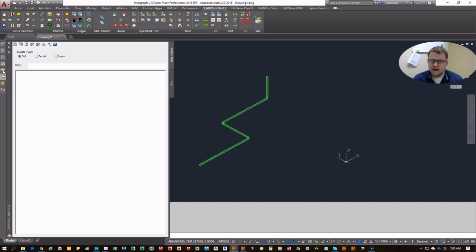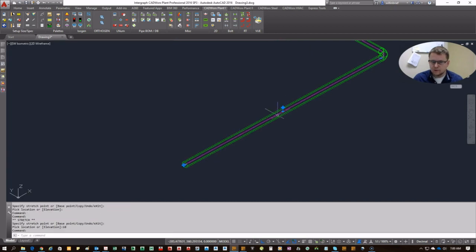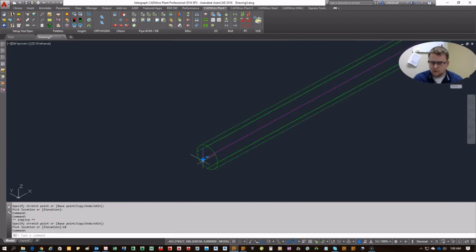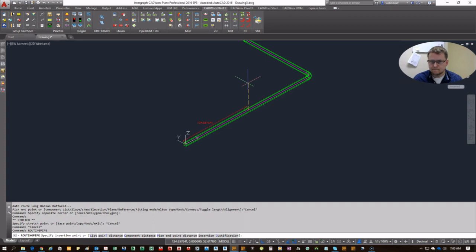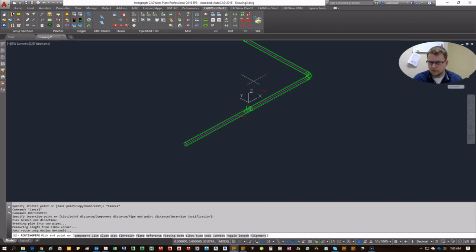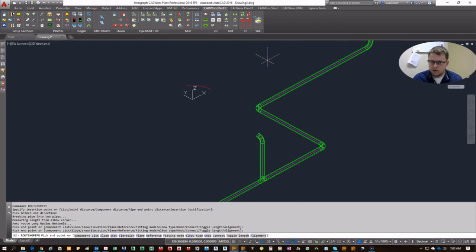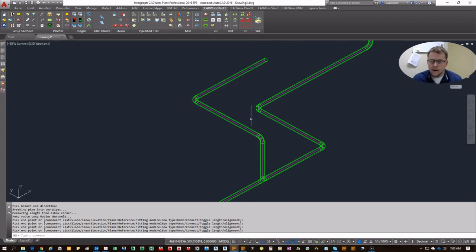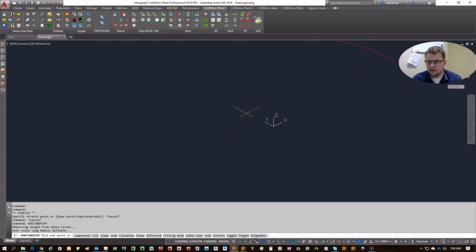So besides just accessing the components from the spec view palette, you now have the option to come here and click on these plus signs, which will continue pipe, in this case, like this. Or it will also create a component, piping fitting, that will let you continue on routing the pipe. But it goes beyond that even. If I come over here, click the plus sign. Now, right now it's going to want to jump into the pipe router and route more pipe from that location.